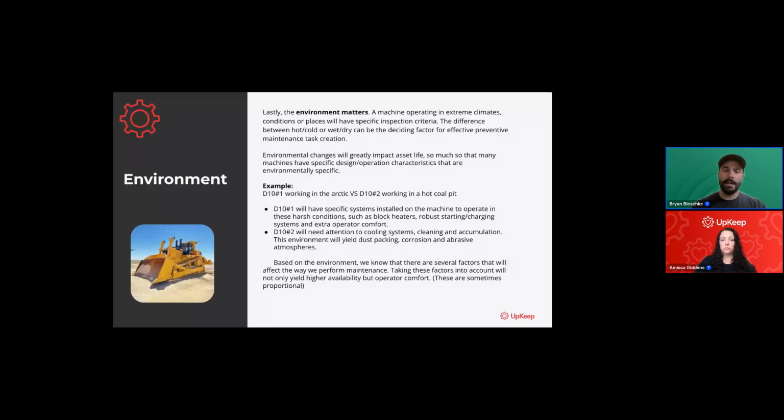If you're working in a high-speed production food manufacturer with perishables, you're going to have machines meant to work in cold environments, because you're going to have cold storage rooms where you're packing out equipment or boxing lettuce or whatever. Conveyor belt materials need to be the correct type of materials. We need to use the right type of lubricants, the right type of steels, passivated stainless steel and all that kind of stuff. So the environment really matters.